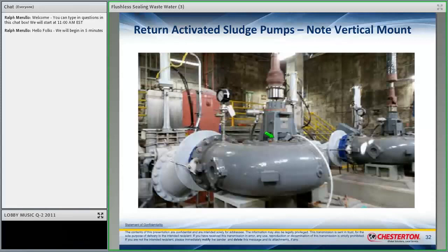At that point, once that pump is started, it's actually pumping fluid within a couple of minutes. The seal faces are lubricated, you should be fine. And also run it when it's shut down, to make sure there's fluid between the seal faces. These pumps are intermittently run. So pumps 2 and 6 are run, and then 3 and 5, and then 2 and 4, or whatever. They're not run continuously all the time. So that was another part of the problem, start-stop.